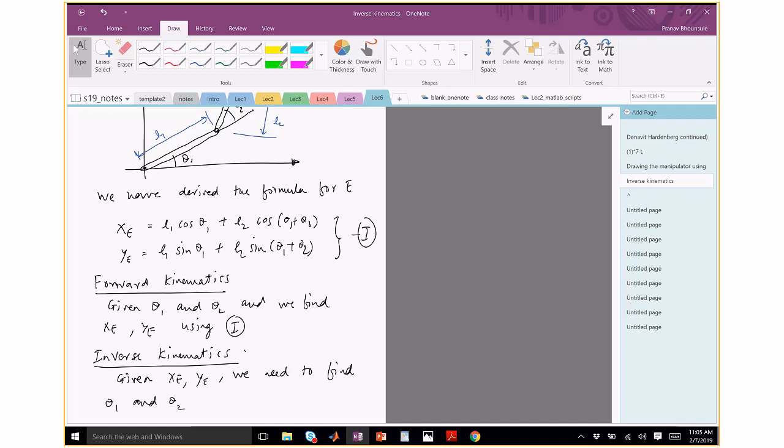So most of the time, the way they design manipulators is to design manipulators which have a closed form inverse solution. So you can actually manipulate the equations, so you can write a formula for theta 1, theta 2, theta 3, and so on as a function of parameters. So imagine designing the manipulators to be able to do the inverse solution. But these days, since computers are fast, you don't have to design a manipulator which has a closed form solution. You can actually use numerical techniques to figure out the solutions to the problem.